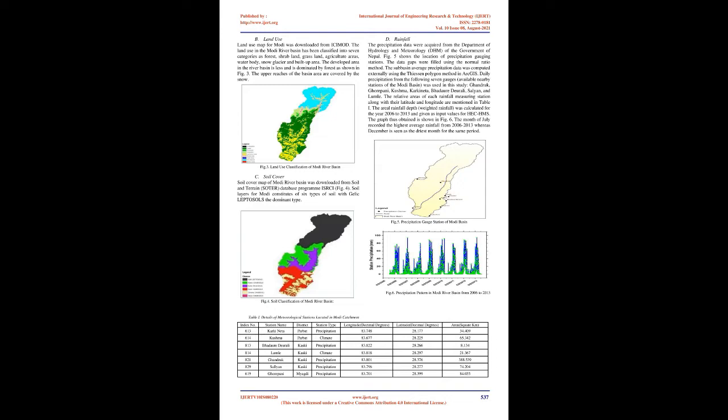Furthermore, in the Kashi River Basin the simulation was carried out by model software HEC-HMS, and 4 types of modeling results in terms of parameters, namely deficit and constant loss parameters, Clark runoff transform parameters, monthly base flow (m3/s) parameters, and Muskingum routing parameters were estimated.